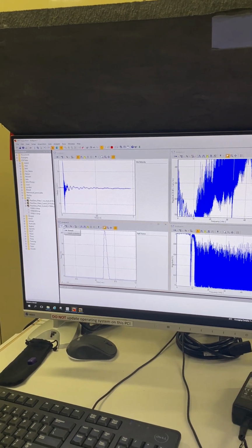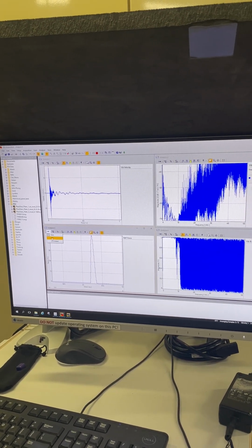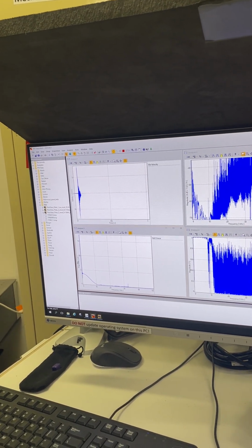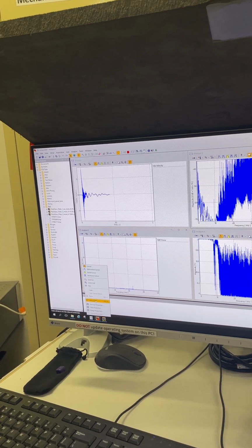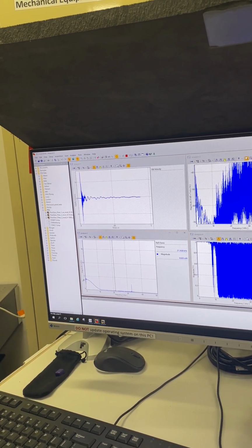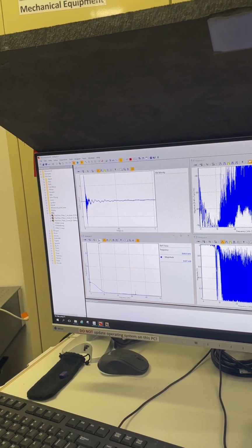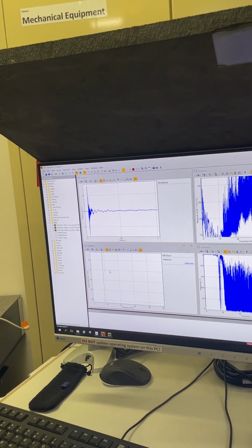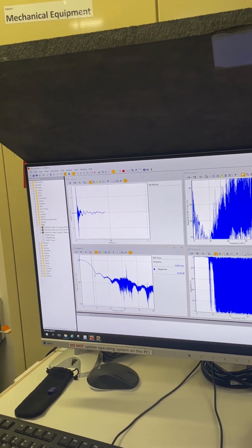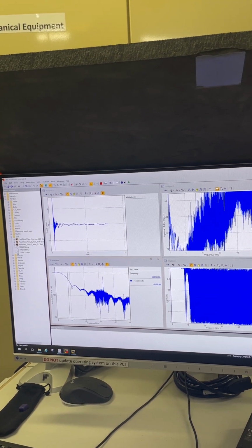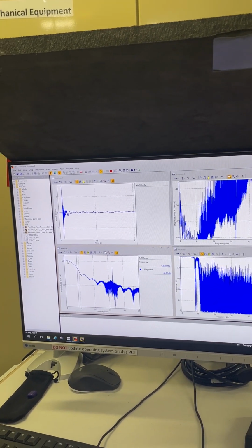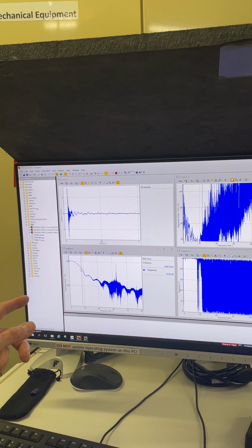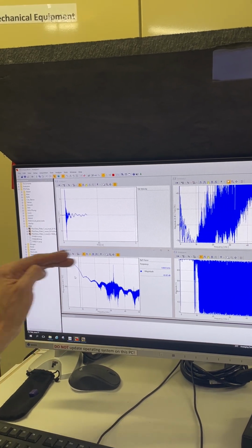The other thing that we should have a look at then is the FFT, of course. When we do modal impact measurements, we're looking for a very nice looking wide frequency range of excitation. This is the characteristic downturn, although I'm looking now in magnitude. So if I look at magnitude in dB and auto scale, then we can see the typical characteristic we have from a modal impact hammer, where we have this first hump, and then a bit of a dead area here and another hump, and so on and so forth. So for a perfect impulse, we'd see a flat line.